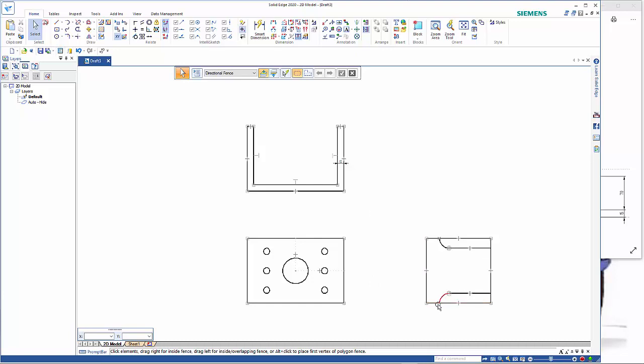So that gives me my point there, just so that it's sort of separated as a front and back area. I'm going to use the split command. So I want to split this line at that point, and as you can see we've got a collinear relationship on there now, and it's joined at the end here, so it's split it quite nicely.